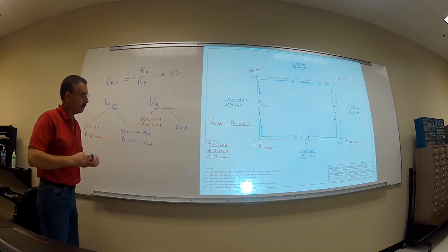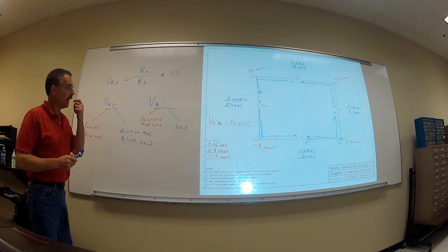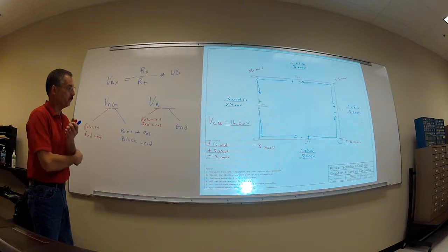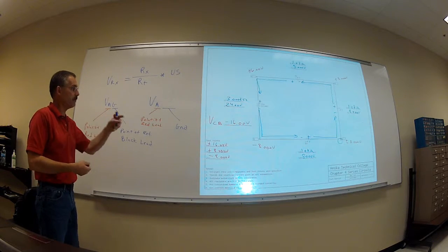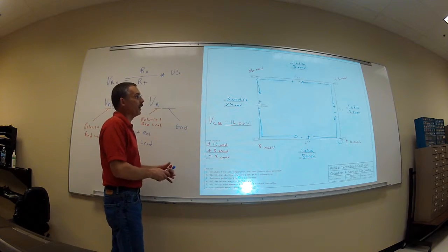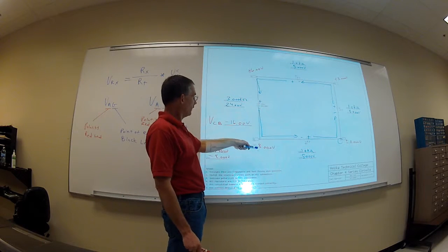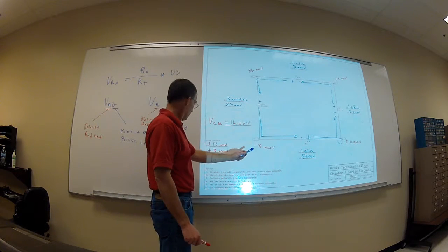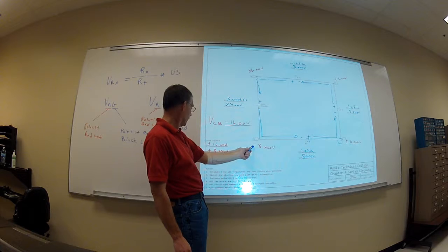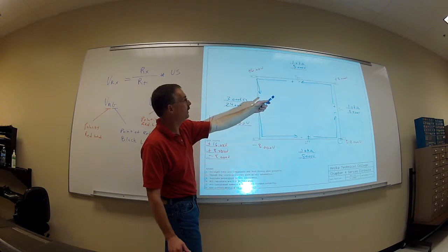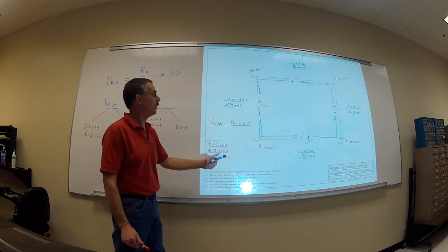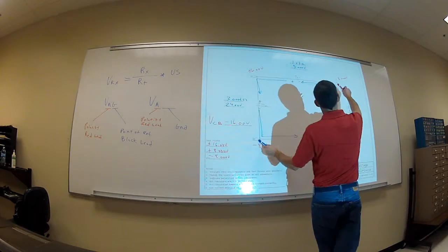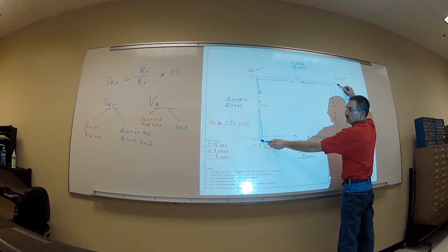So if I said, what's my voltage at test point C to B, just like we did? Another way of doing it would be that I know that test point C is a negative 8 volts. I know test point B is at positive 8 volts. What's my potential difference between those 2 points?